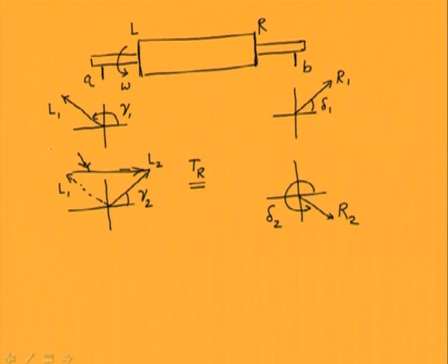So it indicates the influence coefficient AR, because this is the effect of the trial mass in the right plane at bearing A, that is, the change in the response. If we do the same thing at the right bearing, this particular vector is the effect of the trial mass TR on the B plane. So it indicates the influence coefficient BR.